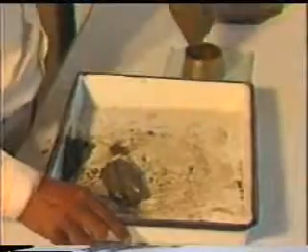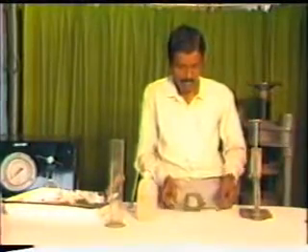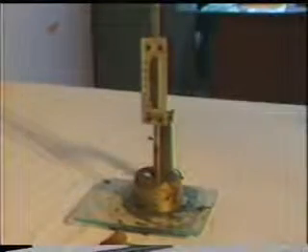Fill the Vicat mold placed on non-porous glass plate with prepared paste. Shake the mold to expel out any entrapped air and level its surface with the help of a trowel. Place the prepared mold under the plunger. Unscrew the clamp to bring the plunger just in contact with the surface of the paste and quickly release to allow it to sink. Note down its penetration reading from the bottom.